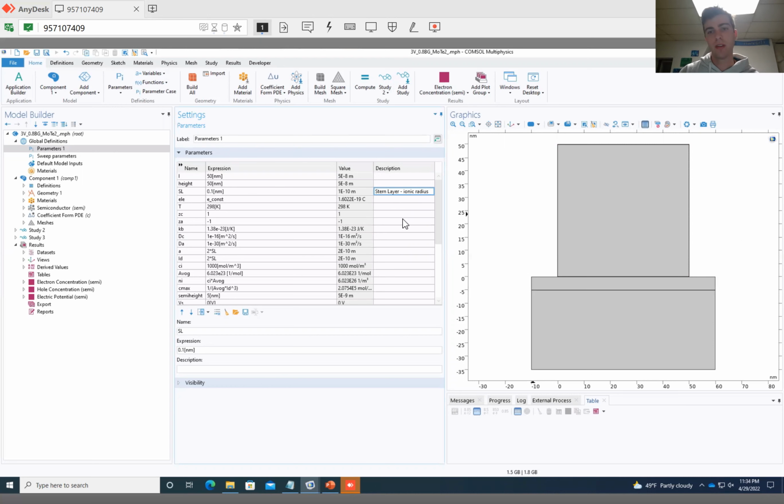So I mentioned that our electrolyte has different ions in it. This is modeling basically lithium ions inside the electrolyte. If we wanted to do something like, say, cesium, we could use a value of 0.2, which is approximately the ionic radius of cesium. This will affect the maximum amount of ions that you can induce into a particular area, because larger ions can't pack together physically as closely as smaller ions can.